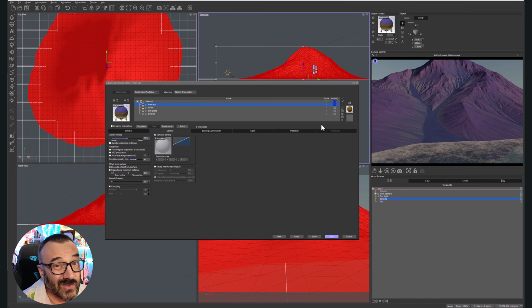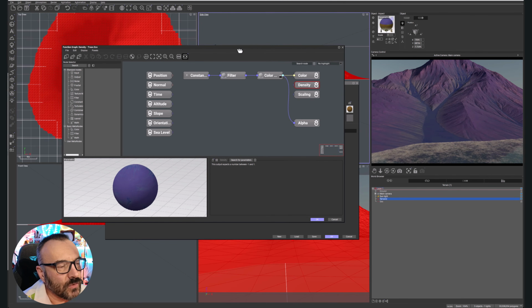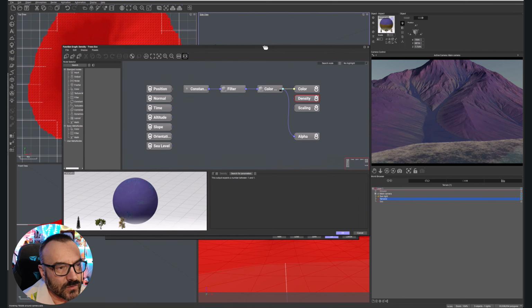And now we're going to a scary place. Scary, for those who do not know, means we're going to use the function editor. One thing I was thinking of was avoiding any function editor in this video, but you know what, let's just dive all the way in and see who can swim. So in parametrics, we'll right click and go to edit functions. You remember in the first video, I said we have multiple layers. Yes, we have first creation, second these editors, and now we're on the third level where we have all of these nodes. Okay, let me show you what's going on in these nodes.